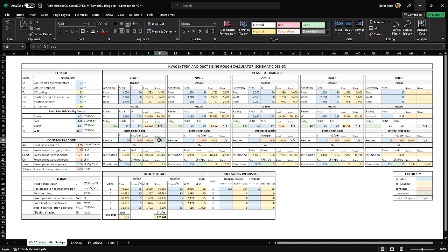Remember, we're asking what's the maximum amount of heating or cooling load we're going to need? What's the worst case scenario? So for heating, let's see how to put this. For heating, if we have the sun coming into the building, which we covered here, that's a gain for heating, so that actually helps us. We have to produce less heat if we're getting it from the sun.